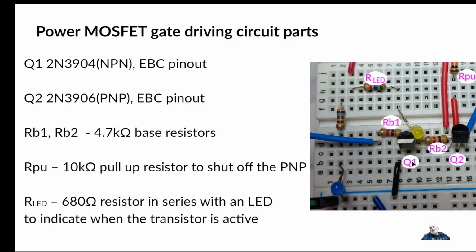wired up so that when you activate the NPN transistor Q1, that's going to turn on and feed this resistor and feed current into the base of Q2, which is a PNP transistor. We don't use those as much, but remember, these are backwards. So this is actually going to pull the MOSFET up to 24 volts. The blue wire here is to the collector of Q2, the PNP transistor, and that one is feeding out to the MOSFET inside the heat box to activate it.